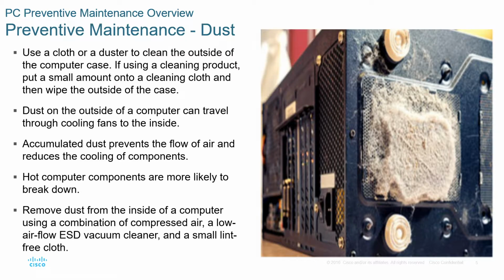You can also use some airflow ESD vacuum cleaners, and pay attention to this observation, guys. If you use a vacuum cleaner to clean out the dust from a computer part, make sure this vacuum cleaner is ESD safe. Most of the time, if you use a random vacuum cleaner, it may discharge a current into your computer components, and that may damage some of your computer parts.